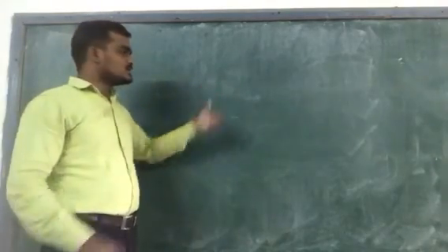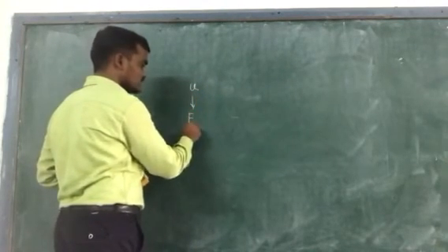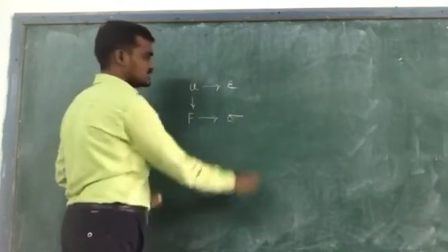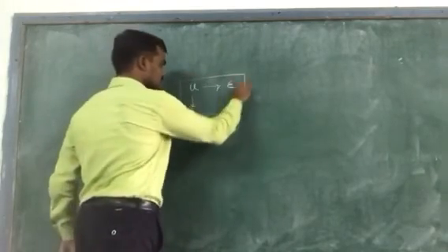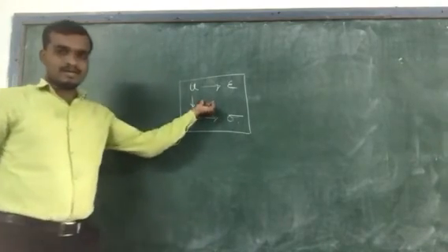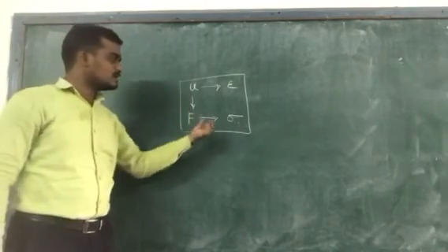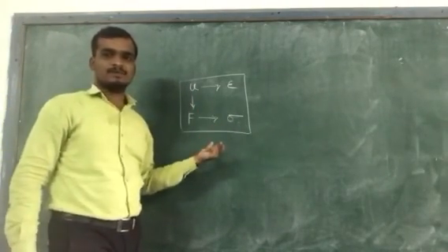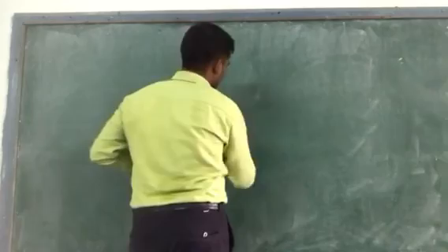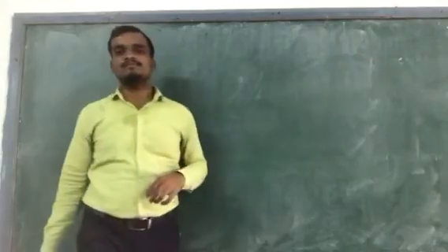By using the force value you will come to know the stress value. So first you will get displacement, then forces, from this you will get strain, and from this you will get stress. We will apply this same procedure to the one-dimensional bar element and find out the stresses and strains in the bar element. So here I will conclude this lecture, and in the next lecture we will start our one-dimensional bar system. Thank you.